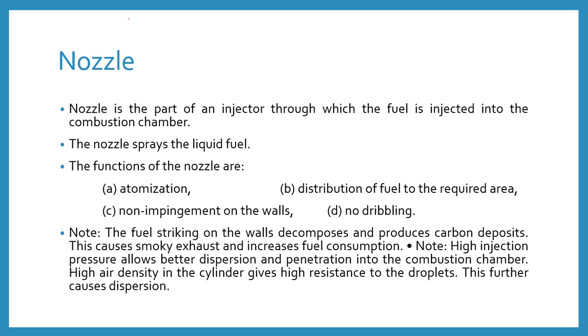So to reduce the smoky exhaust and the fuel consumption, we need to ensure that the fuel injected through the nozzle does not impinge on the wall. As no carbon is deposited on the cylinder wall, the smoky exhaust reduces and the fuel consumption also decreases.